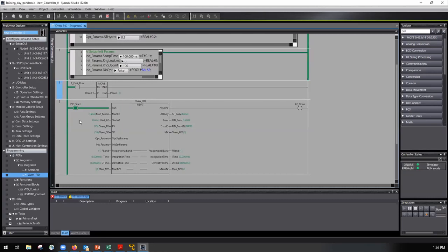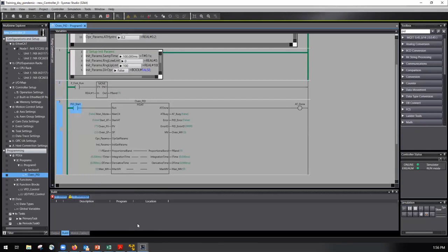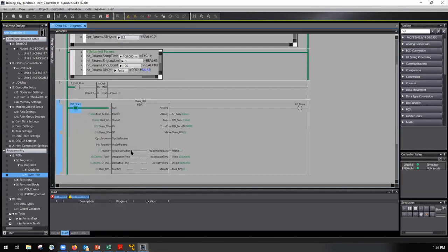Interesting. It should be okay. I mean, you can just turn off your PID block. You can manually write 1 into your P-band, hit enter, and then start your simulator or your PID loop again. And then you can play around a little bit with our variables here, and we still get the same reaction on the output.